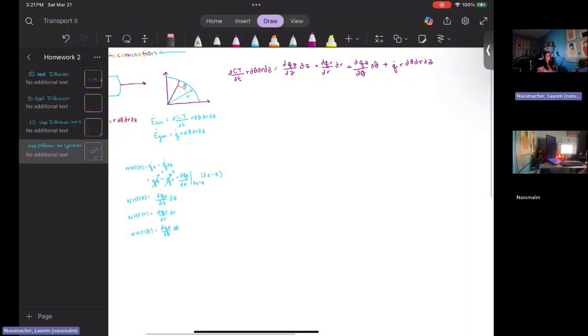And from here, you want to simplify this down. What we can do is use Fourier's law and the concept that our heat flow is equivalent to our thermal conductivity multiplied by an area multiplied by the change in temperature over a change in distance. We'll say it's z for this one. And that area, we're going to say, is equivalent to the radius multiplied by whatever unit we haven't used yet.